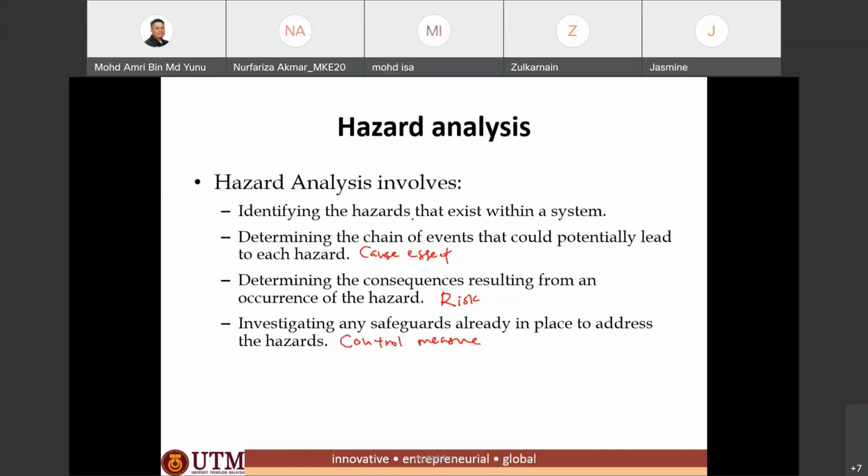So you need to identify the hazards that may happen in the system. In general, you are the expert, like an expert in control system design. Now we are talking about instrumentation and measurement, and about valves. In the system there is a valve. What is the probability of failure of the valve? The probability of failure on demand, PFD, can be calculated from the datasheet, for example.